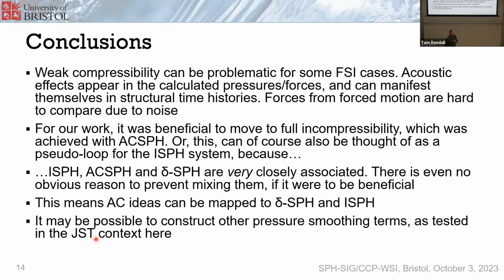I'm not happy with that, because I don't think the max speed of sound is really consistent; it's more a numerical feature of the pseudo time steps. So our pseudo sound speed, which is one of the governing parameters, is just from the CFL condition. We have the time step in pseudo time, we know the CFL condition for explicitly integrated pseudo time. So we can get a stable wave speed all the time in pseudo time. So we're just swapping around the definition of how much of that is in the CFL condition.